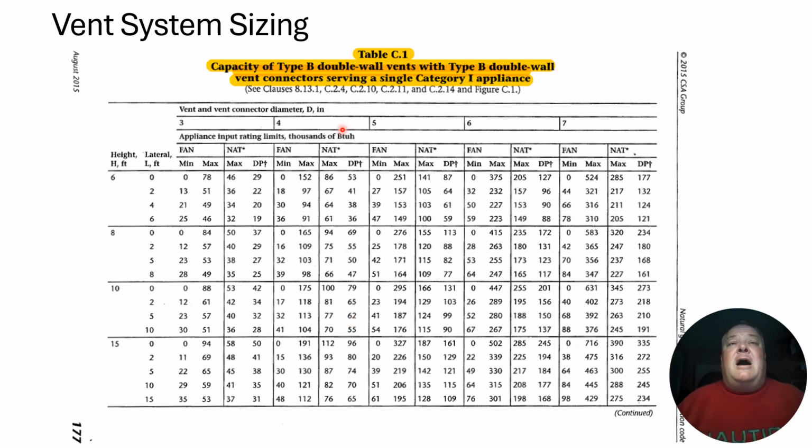And if you look up at the top, those are all incorporated underneath the 4-inch diameter hood, or the 4-inch catchment here. So any of these four numbers, basically, when you go up to the top, are going to tell you that your vent connector size is going to be 4-inch. And so on as we keep going through these numbers.